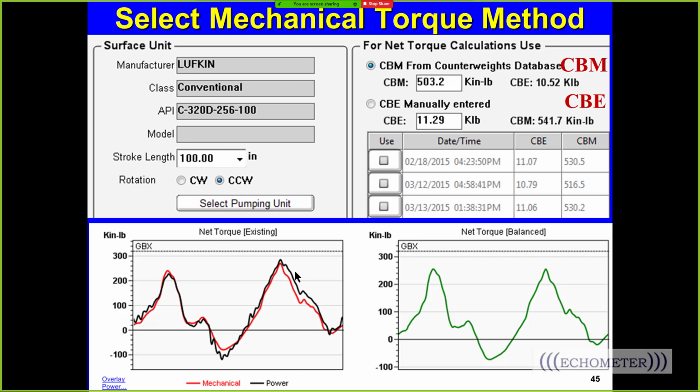But in some wells it can be so out of balance that when the weights are falling, they can generate enough power to make a generated peak and a peak lift where the motor's providing the lift match up. So in some cases, you might pick the wrong peak.